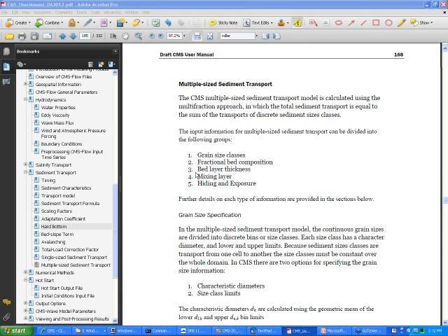So there's several things you can do. You can try a different transport formula. You can reduce the scaling factors. You can reduce the time step for hydro, which is the same for sediment in the case of the explicit scheme. You can reduce your steering interval. And also, you can check your bathymetry, right? Because if your initial bathymetry is noisy, that can cause instability problems. Those oscillations will grow if they're on the order of your grid size. And if you still have problems, then call me.